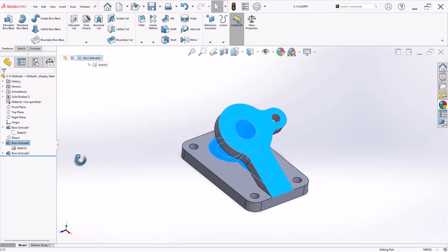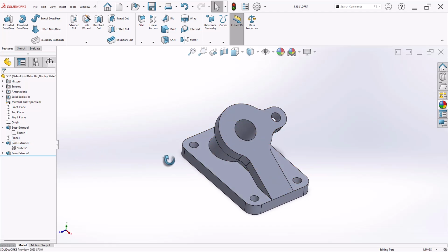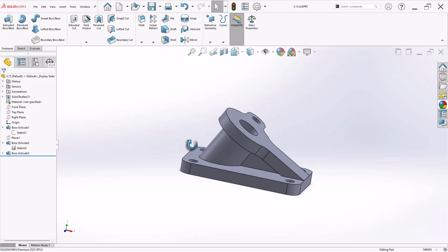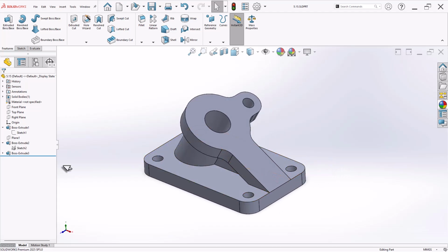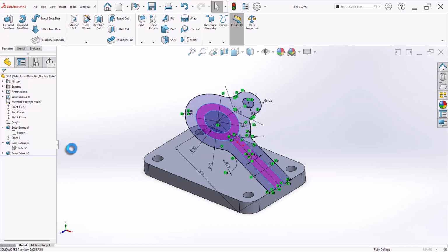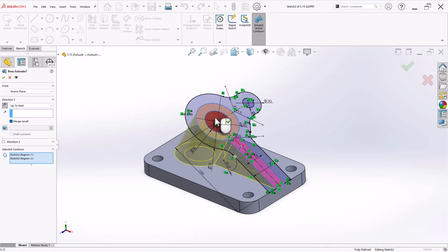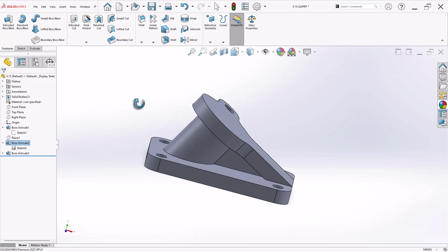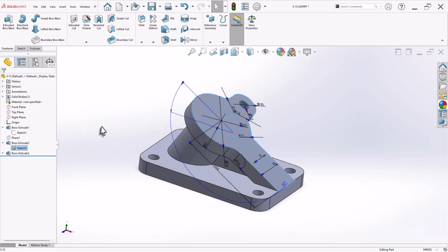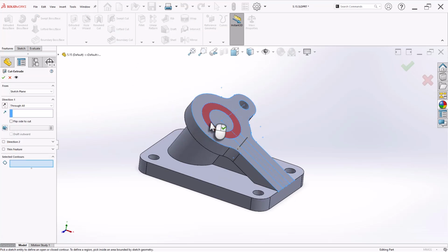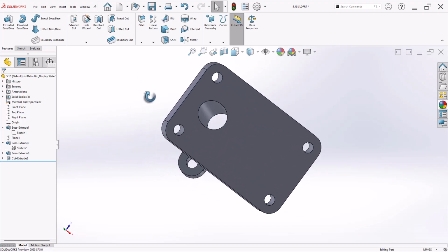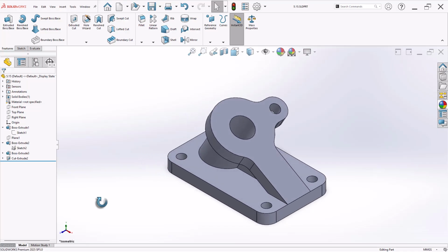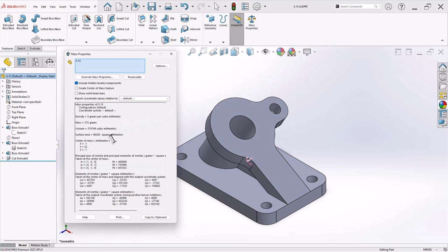Now here one doubt is that this hole must be through hole. Here I haven't created that through hole. So let's try that part. So we need to select that region to extrude from first extrusion. Now again, let's select that part and create extrude cut. This time I will use this, and through hole will be the condition. Now, so we have a through hole here. Now let's measure the volume. So 374749, which is a complete match with the solution answer.